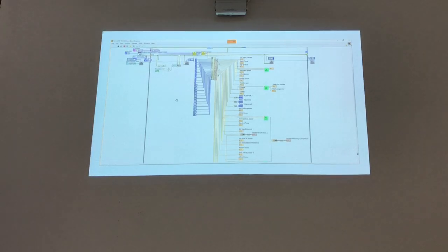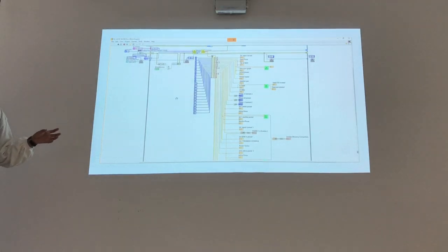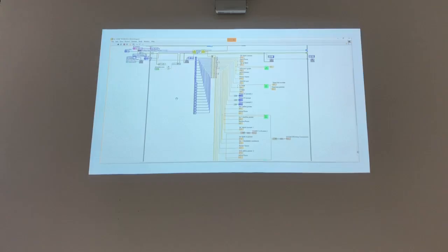And also when you're comparing it to the rated efficiency like I did with the inverters, you can see whether it's too far off or in an acceptable range. I thought the inverters contribute to the overall system efficiency. Yeah. So if the overall system efficiency is really low, it might be the inverter's problem, or it might be the solar panels which require maintenance.